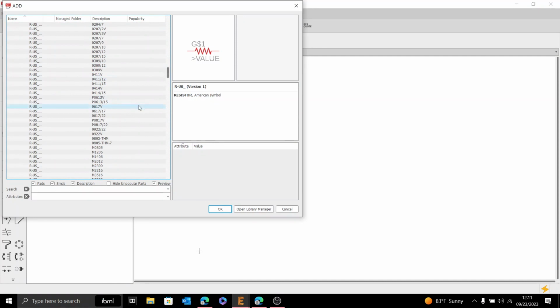So I'm going to pick this one. There we go. So you see here we have our schematic view, which will have the name of the component and its value. And then this will be the physical layout. Now this one's kind of a combo package. So it has 0805, for those that can't see it because it's a little hard to see, and a through-hole mount. So you see here it's got both the pads for an 0805 component along with leads for you to put a resistor with little legs.